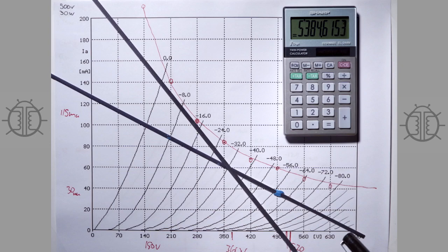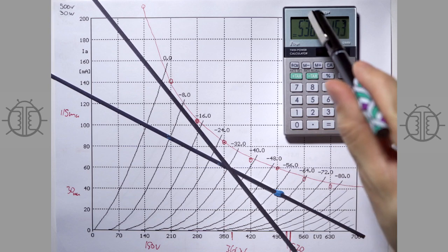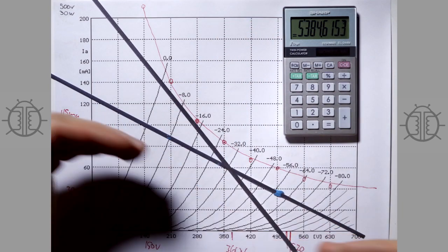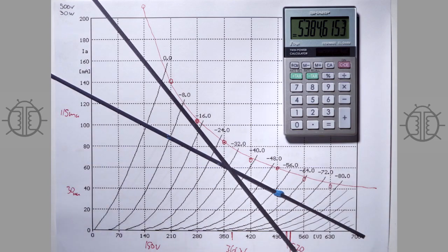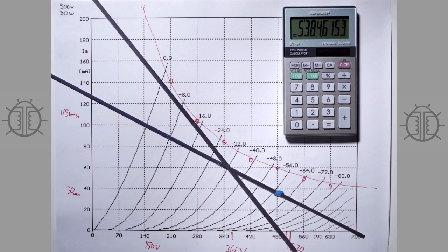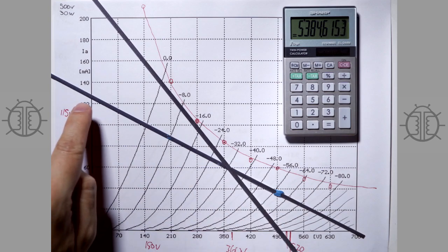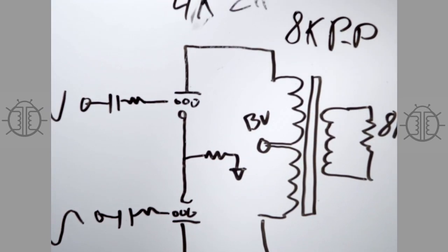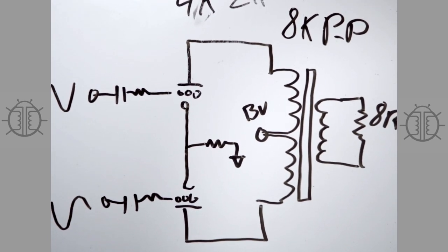It just gets closer and closer to cutoff. And so the transformer gets closer and closer to transitioning from a 5K, this would be a 10K, obviously, because remember this, we're looking at a 5K load line that then transitions into a 2.5K, but the transformer will be rated at 10K plate to plate.